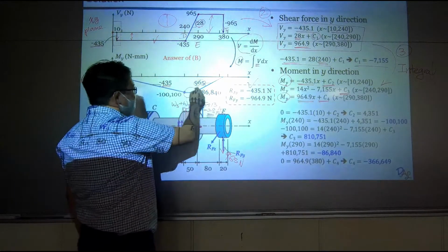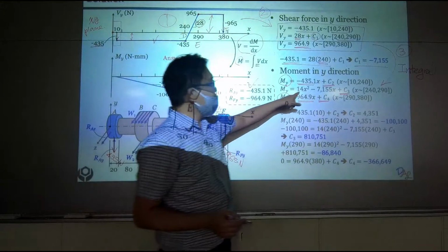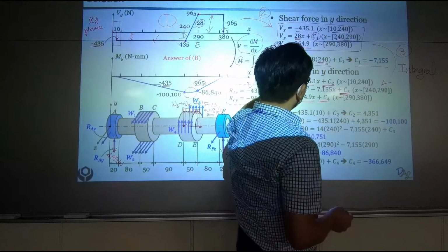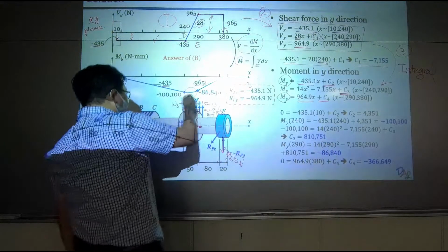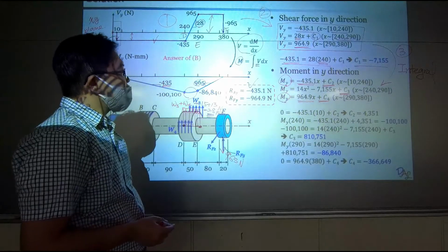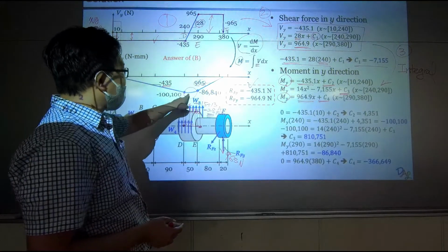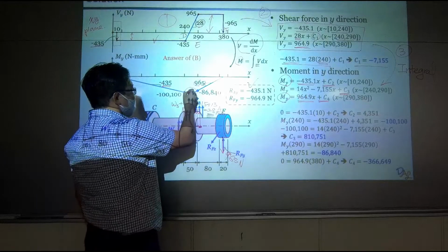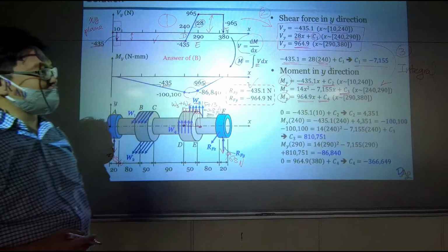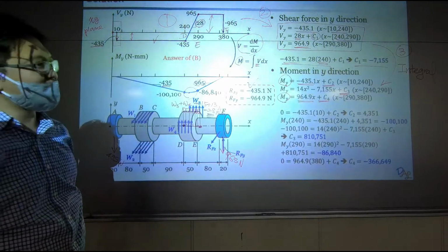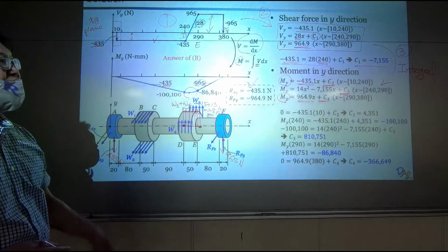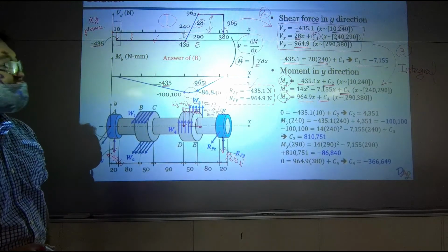And for the center part, it's going to be a second order polynomial if you do an integral from here to here, and supposedly it's going to look like a curve. Later on we may need to solve for the minimum, the worst one right at the center. But not right now. So once you have those integrals, you need to apply several boundary conditions.